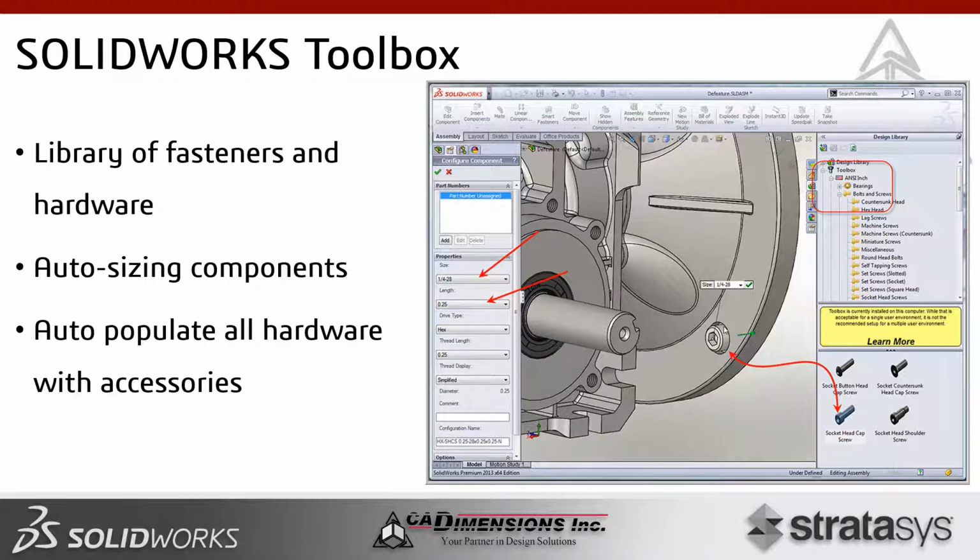What I mean is, if you've got a ton of holes that you need to put screws in, with washers on both sides and nuts, you can automatically populate them. You specify what type of washers and nuts you want to use, and it basically puts all of them in your model. So you don't have to drag in each one, mate it specifically, and bring in more.